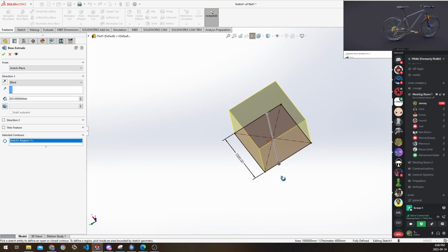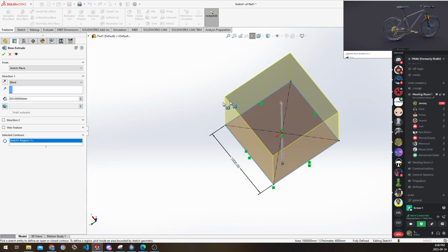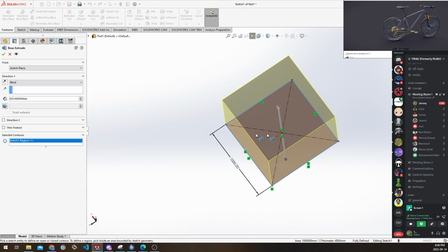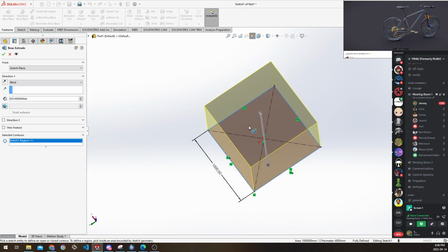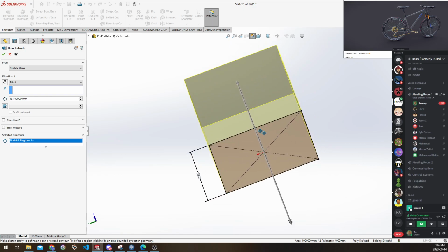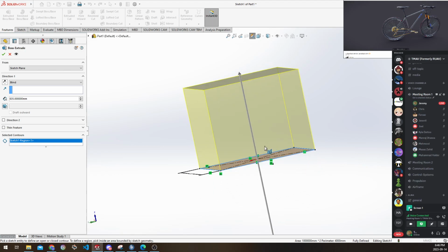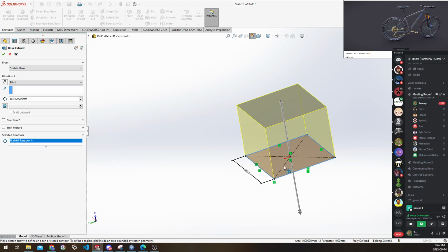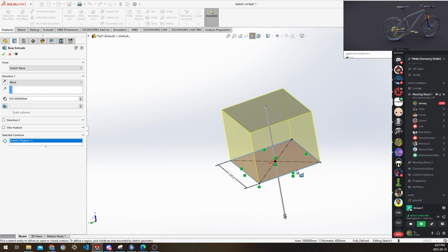The extrusion contour, so this region, this sketch that we made, the square here, is not necessarily where you want to start the extrusion, but by default SolidWorks is assuming that I do. So for example, if I wanted to make a part that's floating off of something, or cut into something but I didn't have a smooth surface to make the drawing from, I may make the drawing from the bottom plane and then jump the cut up into something else, right? That doesn't need to make sense yet. It'll make more sense when we get into a situation like that.